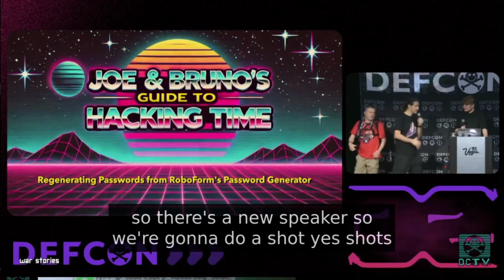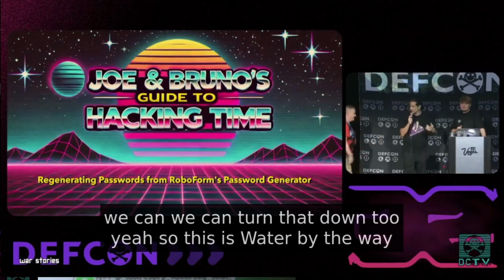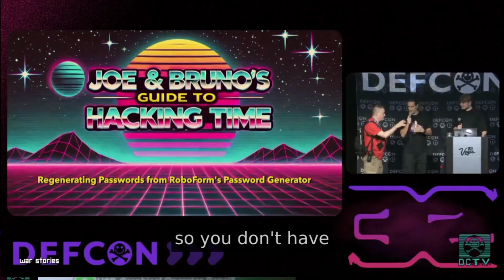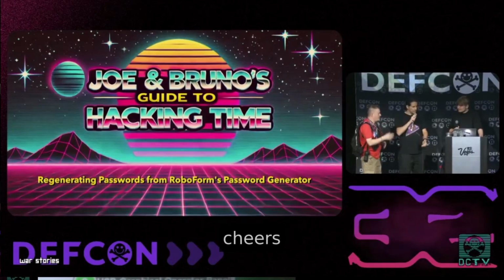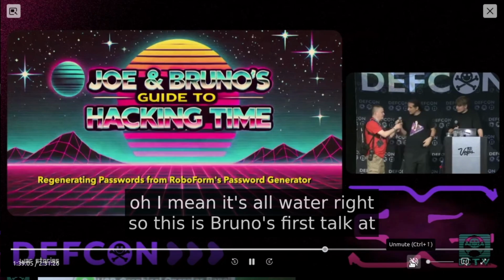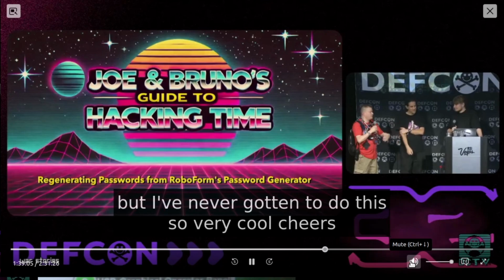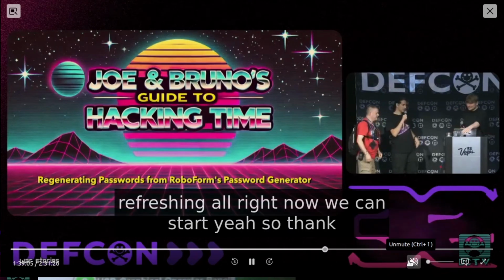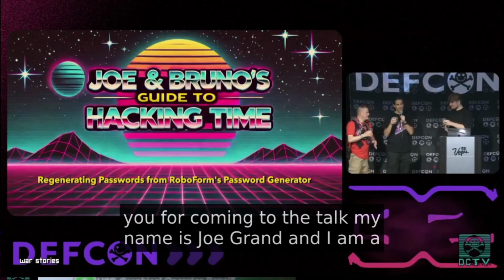Then we want to actually receive that information. So how do we receive it? The typical setup is we have a photodiode and a sound card. But what we're doing is modulating. With the signal generator, we start modulating this thing at hundreds of thousands of times per second. Humans can hear between 20 hertz and 20 kilohertz, so I want that sound. But I want to get away from those low frequencies because there's so much electromagnetism at those frequencies that it's disrupting the signal I'm getting, because we're getting very little light back from the laser that's reflecting off a window or off a computer.